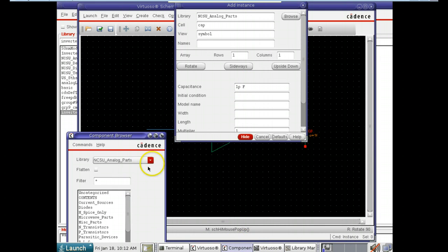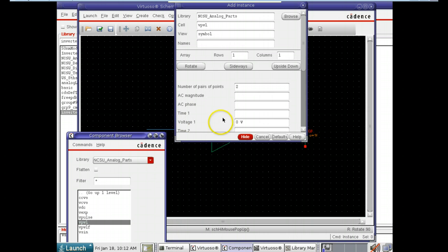Add a voltage source, or excuse me, let me correct myself there. Let's add a signal source. So analog parts. So this time in the test bench we're going to actually use voltage sources, not supply nets. So we'll come in here and you have VDC, and you have pulse and piecewise, and so I'm going to go ahead and use the piecewise. These are pretty awesome.